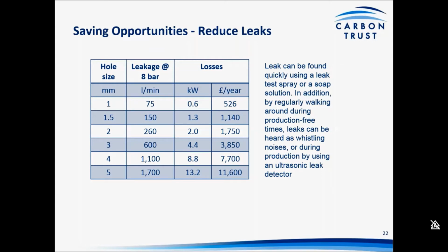A 1.5 millimeter hole, you're losing about 150 litres a minute at 8 bar pressure, upwards of £1,000. As I said, we would use the little ultrasonic leak detector. You're going to find one of those leaks. That's the cost of that covered.